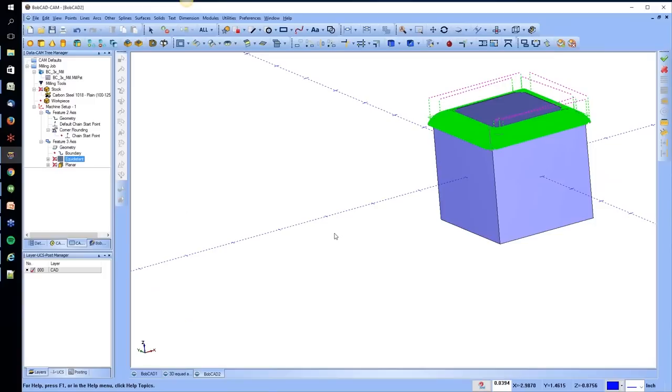So as you guys can see, with toolpaths, you don't necessarily have to use a specific 3D toolpath only on 3D parts. You can also use them on a pocket, a chamfer, a fillet. It's just giving you those options to use other toolpaths that might save you some time by going into that 3D option, even if it's just a solid model of a 2D pocket, and using one of the 3-axis roughing options.